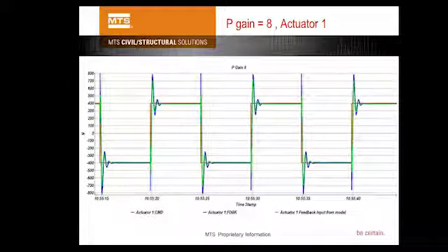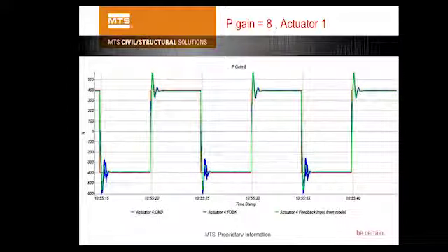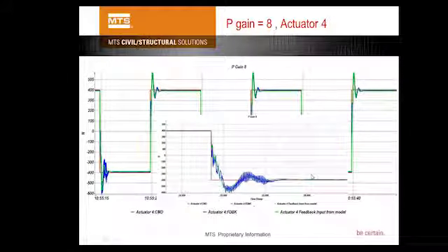So that's when you go up to peaking equal to 8. Again, this is more aggressive peaking, and you see the overshoot is now larger because it reaches about 800 Newton. Before it was 500 or 600. So with more aggressive peaking, we can still capture that behavior. And you can see here that's where it marginally becomes unstable. If you look very closely at the model performance, it actually also shows some of that behavior.